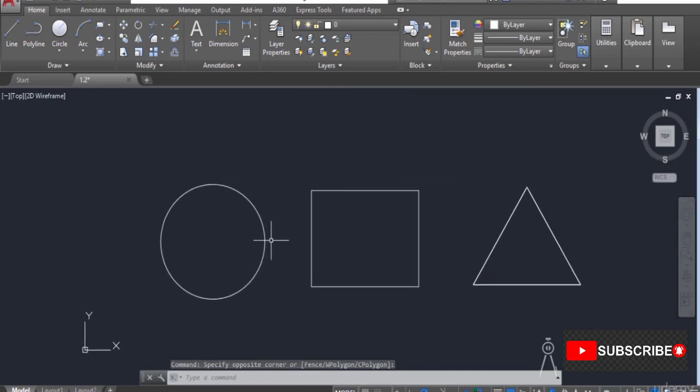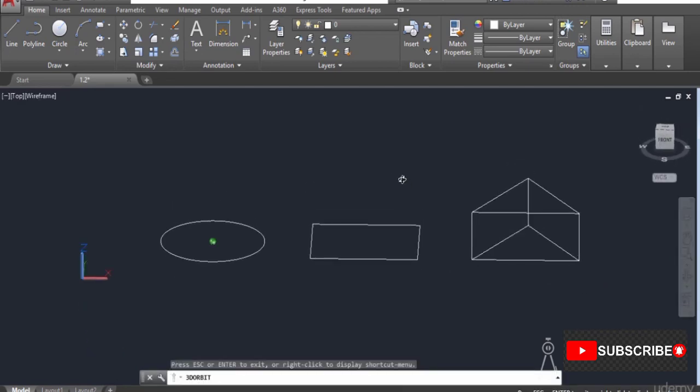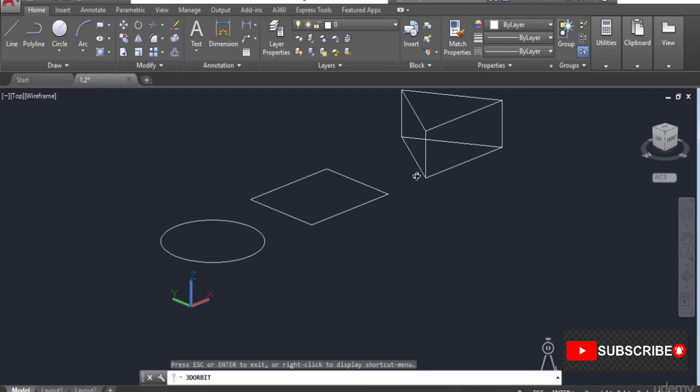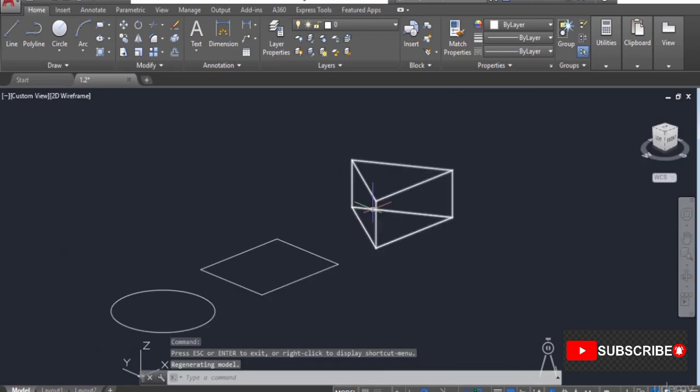We can also access the 3D orbit tool, and using the 3D orbit tool, you can see this drawing from X, Y and Z axis. Currently we are able to see this drawing from the X and Y axis, or from the top view only, that you can see here. But if you want to see the height of this drawing as well, simply go to the orbit tool in the navigation bar, select it, and now orbit your drawing just like this. Now you will notice that the triangle is actually a 3D shape with a certain height. So you can orbit the drawing to see it.